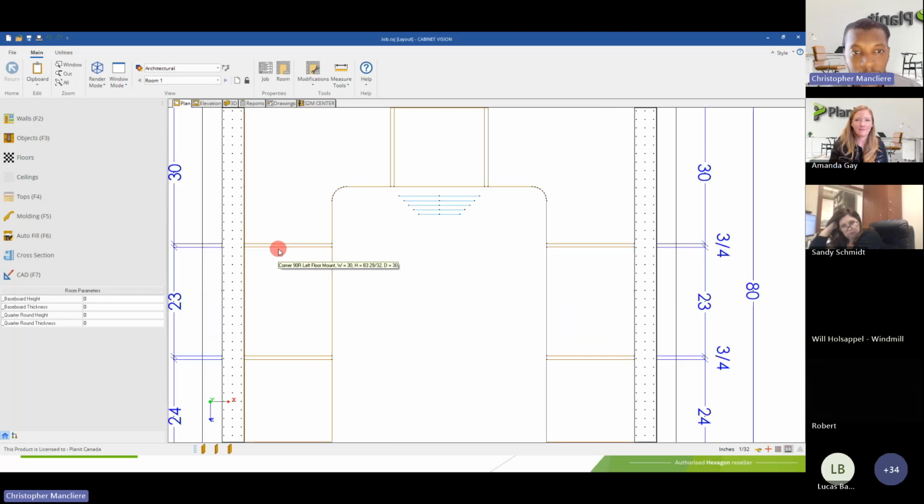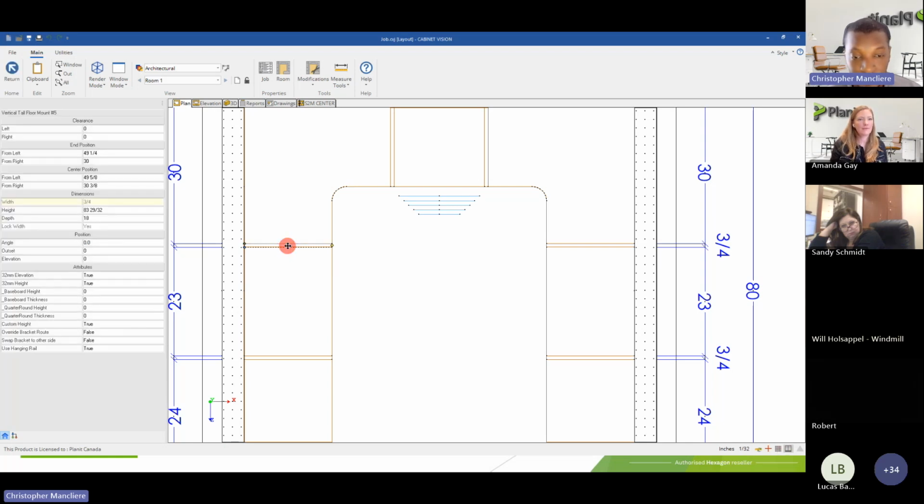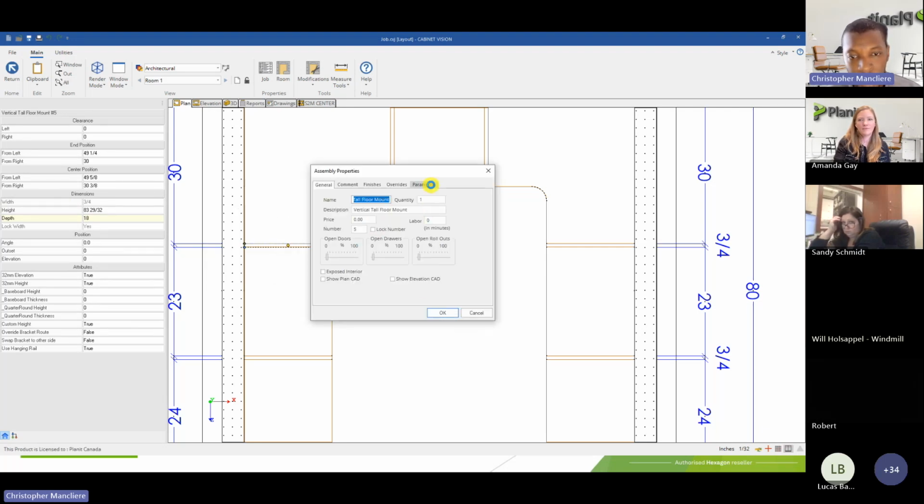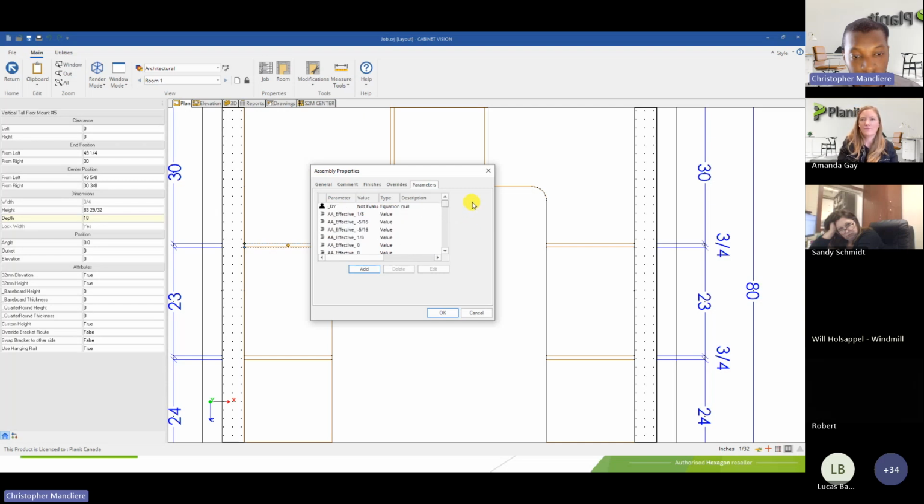Yes. So as a best practice, especially if your material tends to vary a lot, this one is assuming that you have something very close to 3/4. But if there's a difference of a whole millimeter or 1/16 of an inch, you could make the thickness actually parametric. And in the new closet catalog that we're sharing, if I check the parameters of the dials, I believe this one is already set to check the material thickness. So let's see.